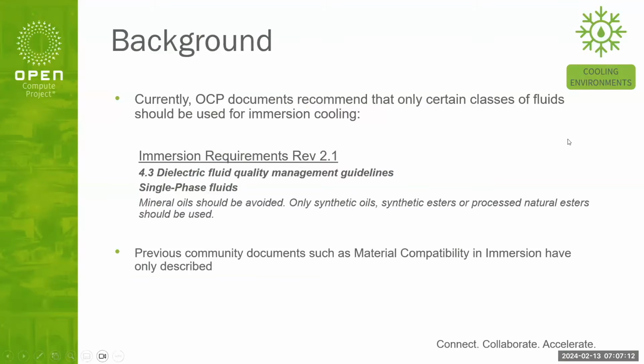So at the moment, OCP immersion documents recommend in different ways only certain classes of fluids for immersion cooling. One of the main examples is in the immersion requirements document, the current revision 2.1, in section 4.3, which describes dielectric fluid quality management guidelines.